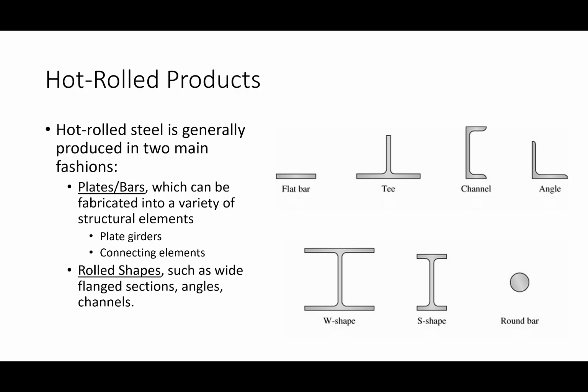I think there was a tour that we had, either last year or the year before, where we toured the Nitro Bridge, the one on Interstate 64 that they just finished, you know what I'm talking about? That big old plate girder that carries traffic from exit, what is it, like 44 to 45? That's a plate girder. So that's not a rolled shape. They actually take plate and weld it together to develop a customized shape. And when you have a really heavy load demand, you kind of need to do that. For buildings and whatnot, other than a few transfer girders and things like that, generally you're just using W shapes or general rolled shapes, which is what we're using.